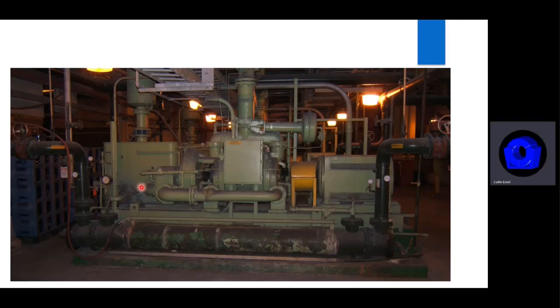And the seal water is pumped out of this tank through this heat exchanger here, and then back into the seals up through this. The cooling side of this shell tube heat exchanger is typically the same source as the main condenser in a power plant, which is either from a cooling tower, river, lake, or ocean typically.